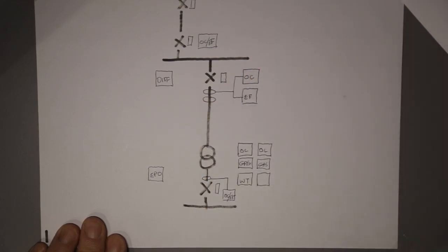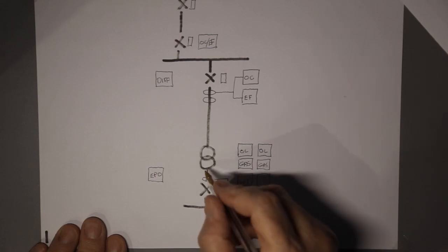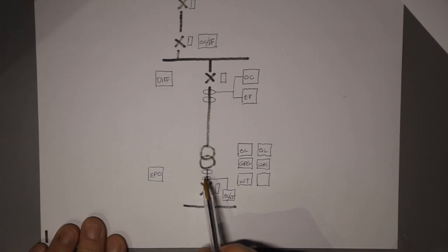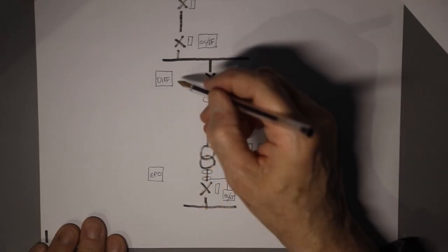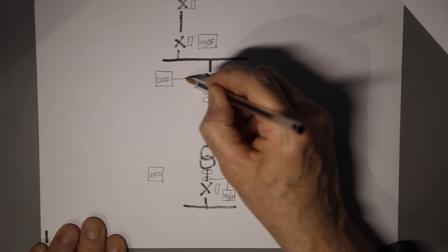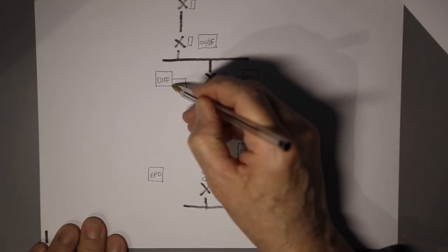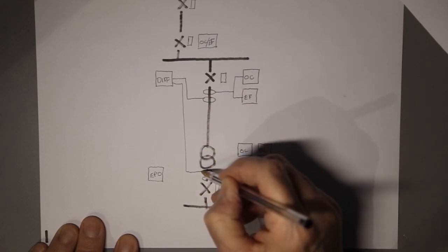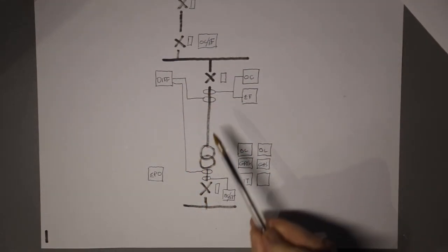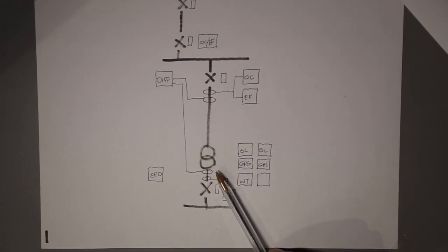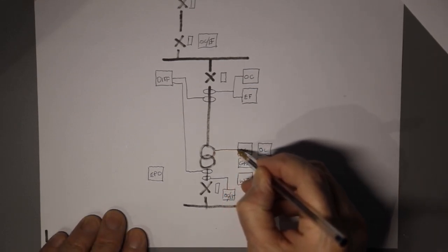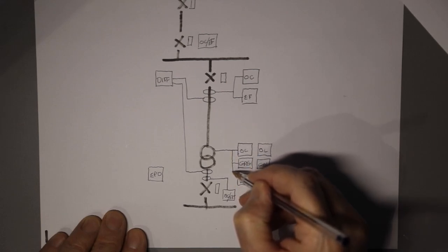Now, we don't know with differential protection what the zone is, but the block protection diagram will show the zone. So here I'm drawing another current transformer and connecting these two new current transformers to the differential protection, and that goes right down to the second CT. So now we can see that any fault in that zone between the two will cause the differential protection to trip. I'll describe the issues with differential protection, particularly for transformers, at another date.